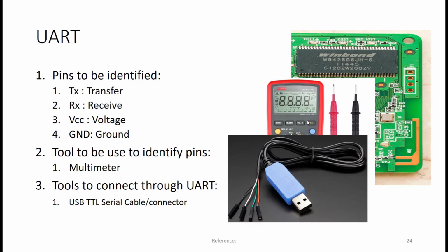Additionally, you also need to understand what the baud rate of this UART connection is to get the most significant data out of the UART connection. If the baud rate is not known, you might need to read the data sheet, the user manual, or the service manual of the device to understand the baud rate. Otherwise, you will not get proper data from the UART connection.